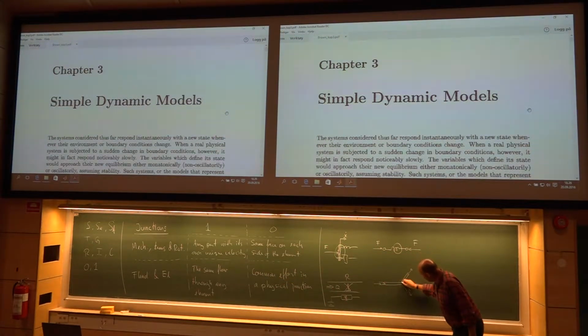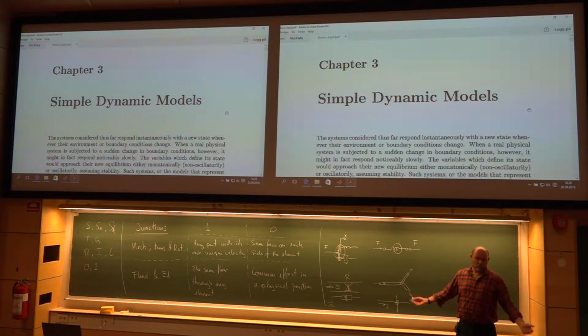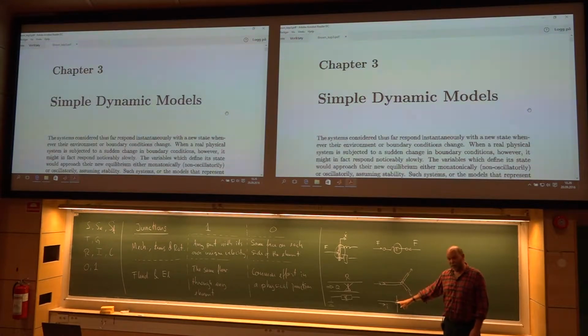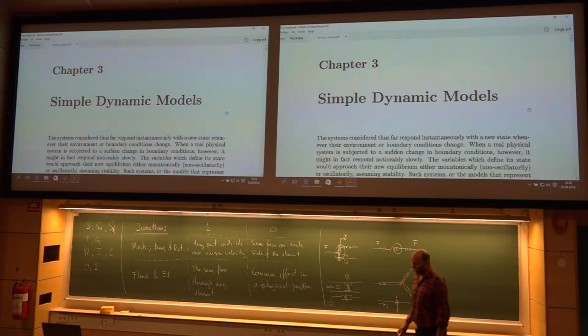So here you will insert a zero junction. Or an electrical circuit, you will typically have some junctions, and again here a zero junction. You will have the common voltage at this point, regardless of any way you are looking. So here the current I is moving, and then can spread out through any of these branches. We don't know how, but we know the voltage is the same, regardless of the path it chooses further.